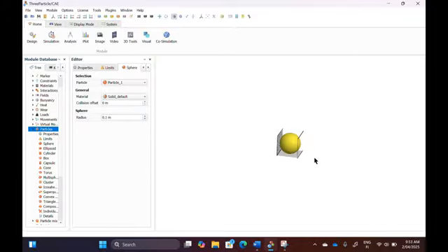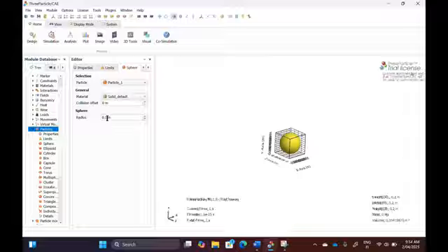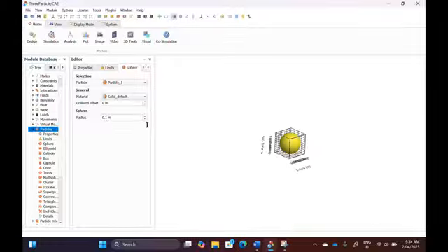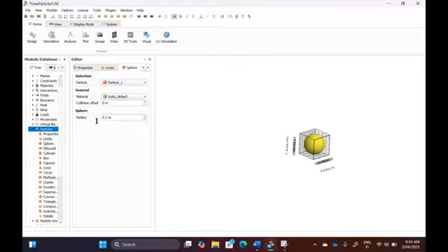It's quite big. Let's say we have a particle with 2 centimeters diameter instead, because let's start with bigger particles. The smaller they are, you remember, the time step decreases. Small particles, small time step, takes forever to compute something. The bigger the particle, the better. Let's start with a 2 or 5 or 8 or 10 centimeter particle. Let's say 1 centimeter radius, 2 centimeter diameter.